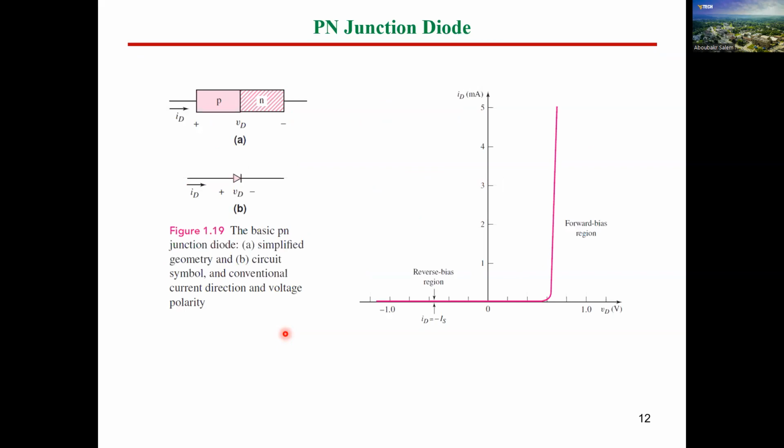So now, guys, if we would like to draw the IV characteristic of the diode, we will just give a quick hint now, and we will discuss it more in depth in the next class. We said in the forward biasing, forward biasing means voltage positive, and this is the current here. This is the positive value of current. So there is no current flow, or the current flow can be a very small value while the voltage is less than the barrier volt. And once the volt is greater than the barrier volt, a current will flow with higher values.